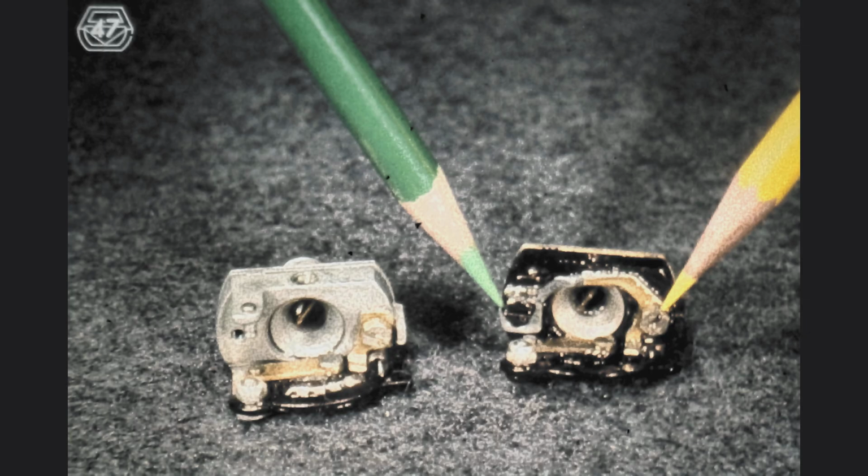With the old-style shoe on the left, it becomes necessary to slowly and gradually tighten the screw, reposition the shoe, then give the screw another bit of a turn, again reposition the shoe, until finally you have hopefully achieved a condition which does not allow any side play for the rotate detent.